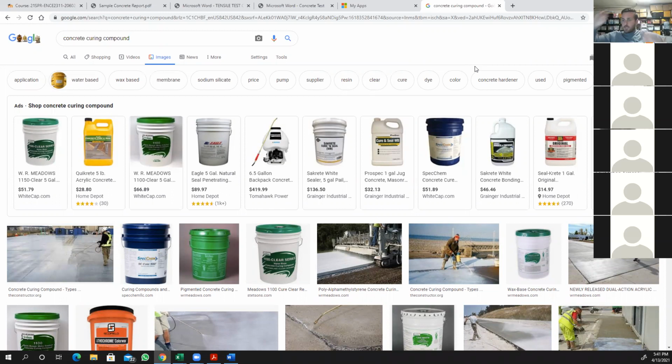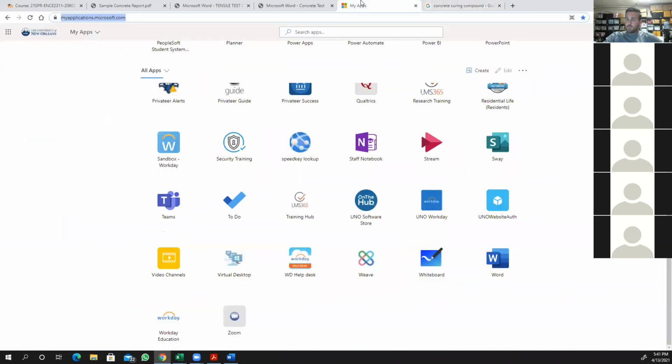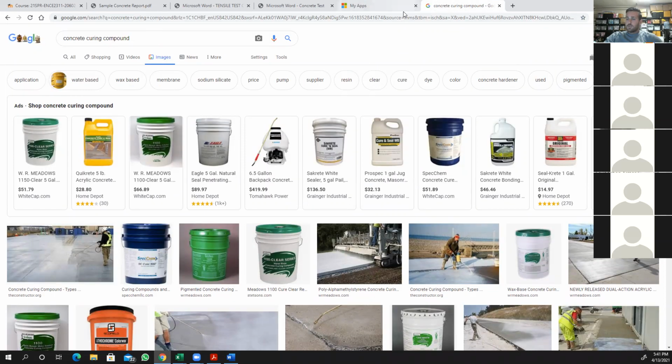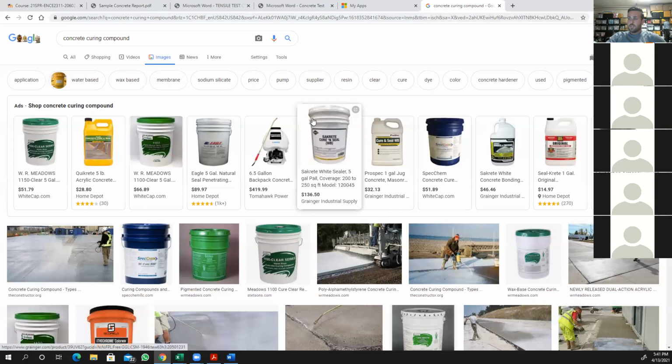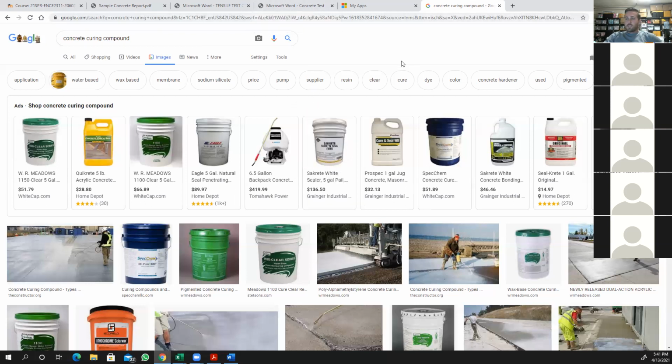When I was working on my master's thesis a couple of years ago, I was looking into rehabilitation methods for structures in or around the seismic zone, especially in California. They use carbon fiber and they wrap the concrete columns that are weak and need to be rehabilitated. The carbon fiber adds additional strength to your column or to your beam. So there are ways to